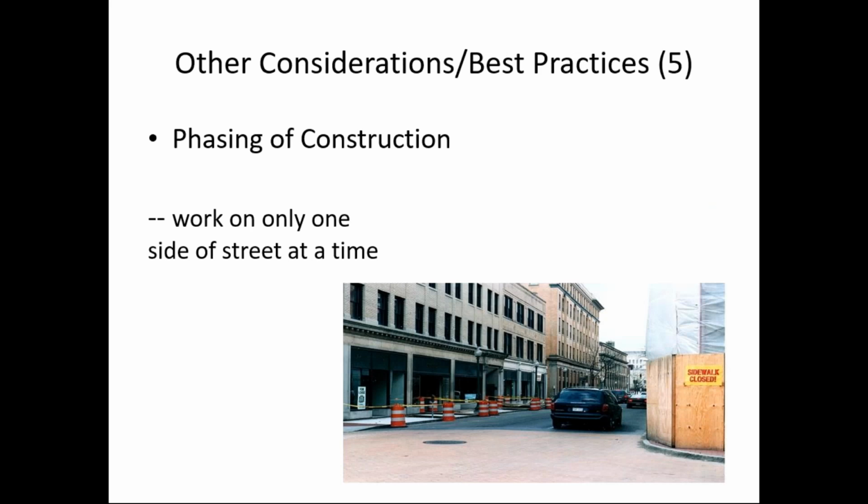Work on only one side of the street at a time. Notice in this city, it looks like we have a building construction project closing the sidewalk on the right here, and a street department or public works project which closed the sidewalk on the left side. And so this street is now totally inaccessible. And I'd be concerned about an ADA suit in that case. I suspect the businesses are not very happy either, and there's also a bus stop at the end of the block here in the distance. The transit agency is probably not happy either.